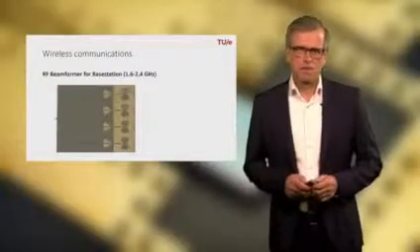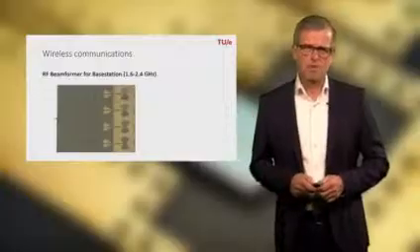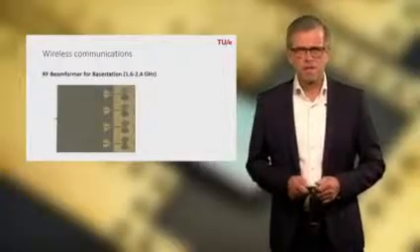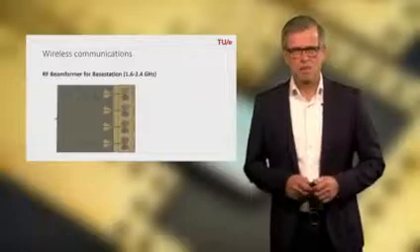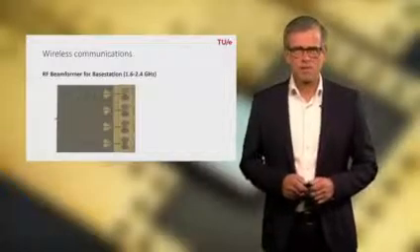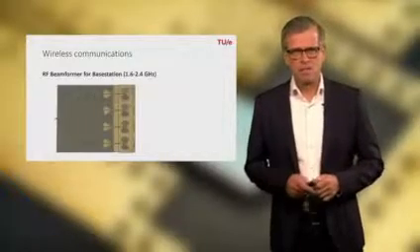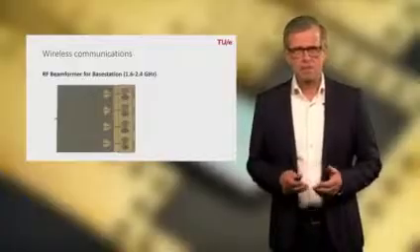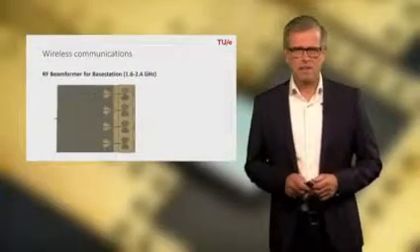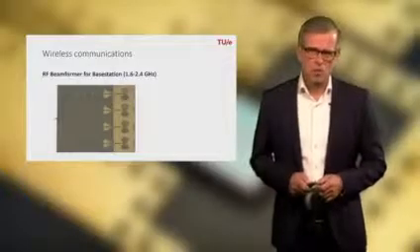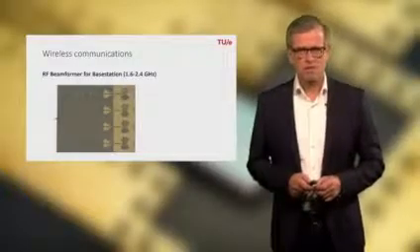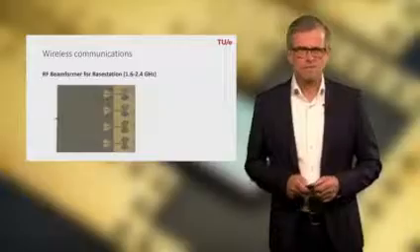It's a system that we developed in my group with students. It's a board where you recognize on this side, in the red box, 4 antenna elements which are printed on a PCB. In this case they represent dipole-like antennas. You also recognize a circuit which is a power splitter, so it has 1 input and 2 outputs.